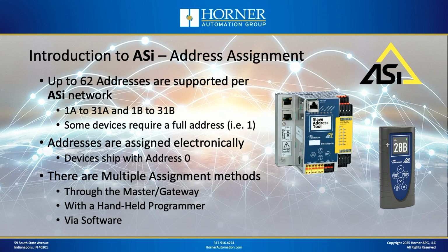Now there's multiple ways in which you can assign the address. You can do that through your master/gateway device. Okay, that device typically has the ability to assign addresses built right into it. You can use a handheld programmer, which is extremely handy and very fast, but it also is an extra tool that you would actually have to source. Or you can do it in software. Okay, so there's multiple ways of doing it, and I'm going to show you how to do it today just using the master/gateway, since you're going to have one of those in every system.